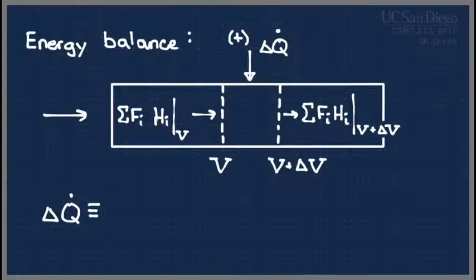You could also have something like an electric heater, and then this form of Q that we're going to introduce is not accurate. You'd have to find one for an electric heater. But almost always this form of Q is because there's another fluid outside your reactor that's either adding or removing energy. The first term that's there is a U. That U is the same U that we had before, which is the overall heat transfer coefficient.